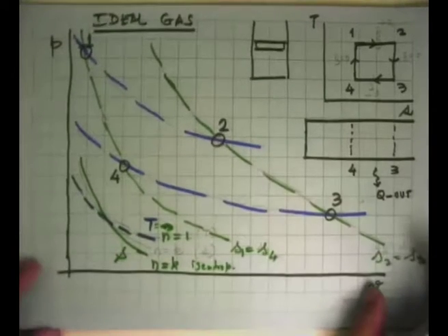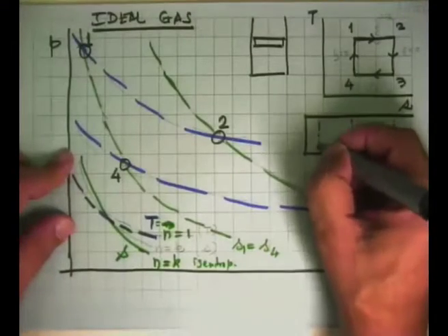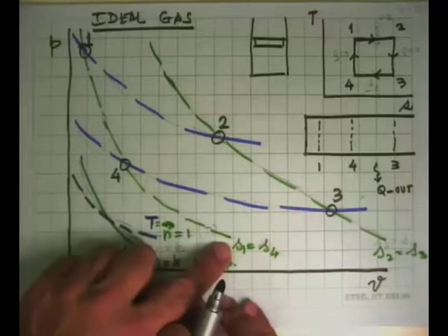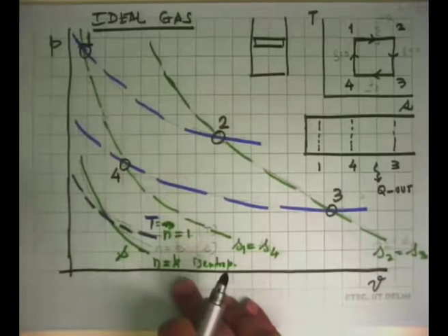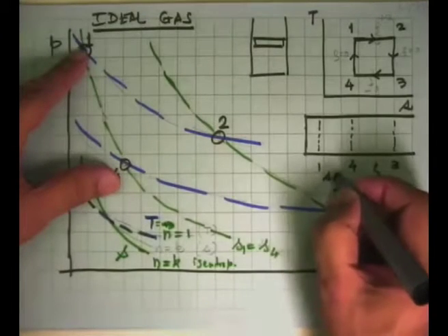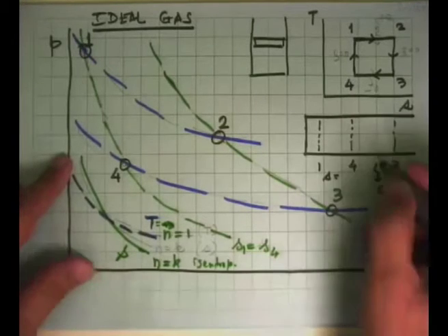That's one thing. 4 to 1, the piston further moves up and comes to state 1. This is an isentropic process. That means there is no heating, no cooling; it's adiabatic and reversible. So ideally, if there was no friction, it could go from here to here. This is isentropic compression. That's fine with us.